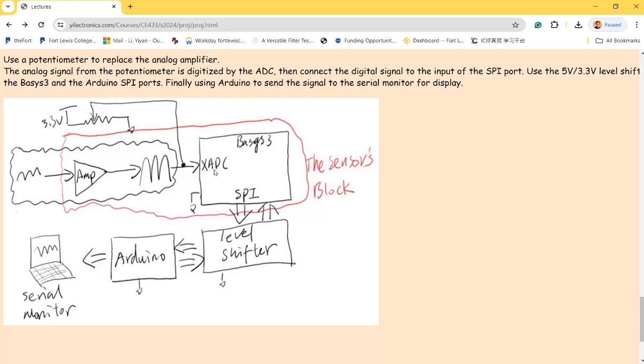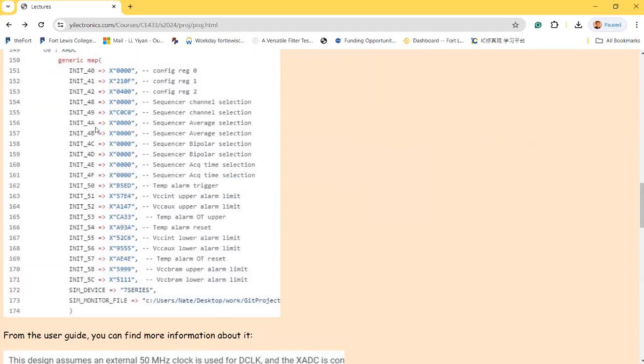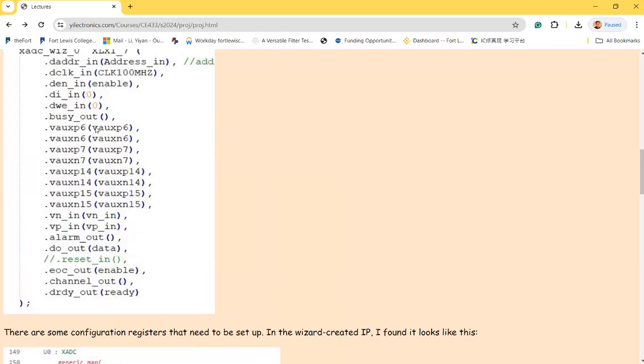If you turn the knob to one end, probably clockwise, for example, I don't know which one, it depends on how you wire them up, it's connecting the potentiometer's output to 0, right? So the LEDs should be off, showing 0. If you turn it all the way on, it should be all ones for the LEDs. And the digital output of the ADC, if you look at the example code here,